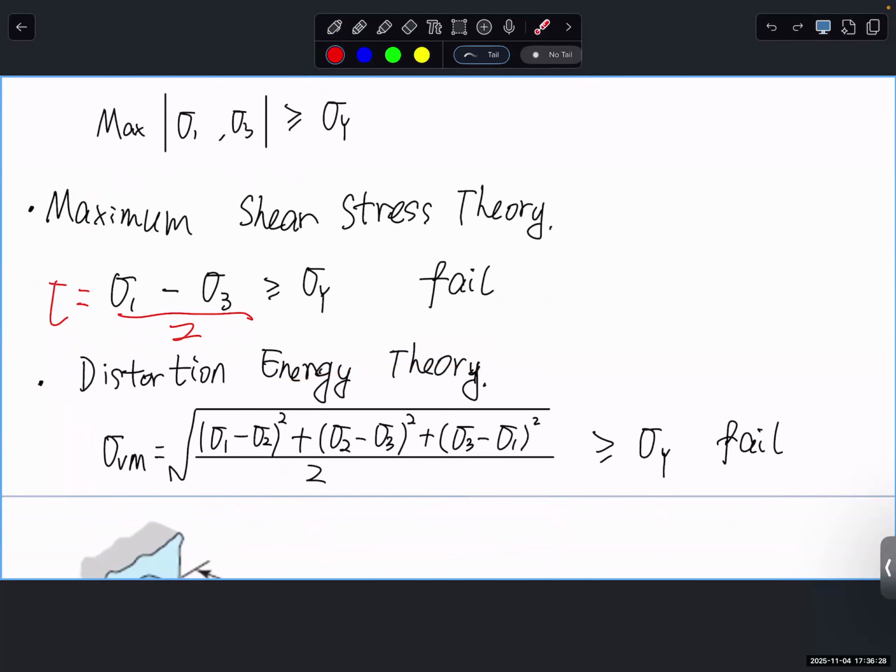For each material, we cannot really do it for different applications, but what we have is that in the lab, we can do tension compression tests. So you fail it, it has a distortion energy before it fails. So we know that distortion energy, and in your own application, let's say you have a tooth and you apply different force, then you know what the distortion energy is in your own structure, and you compare the distortion energy in your own structure with the tension compression test of the material, and know when it will fail.